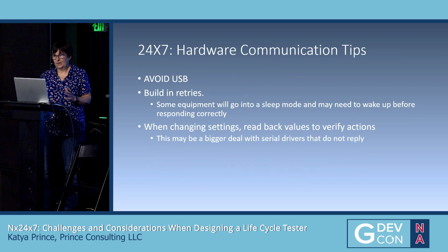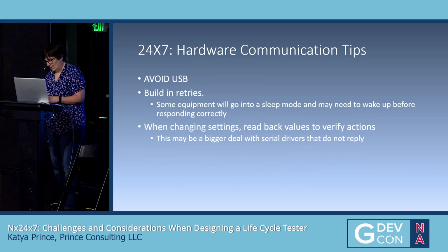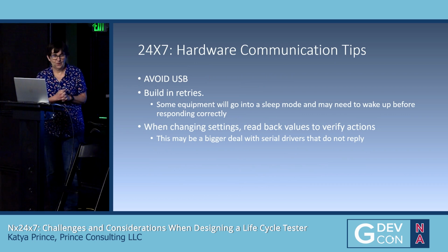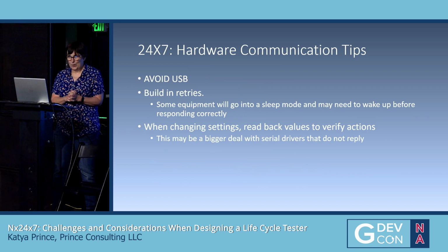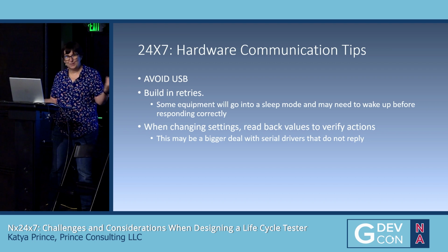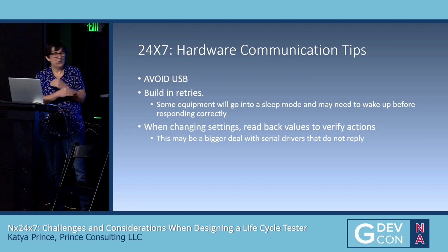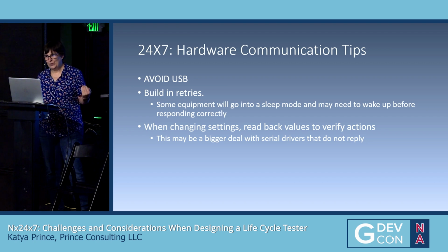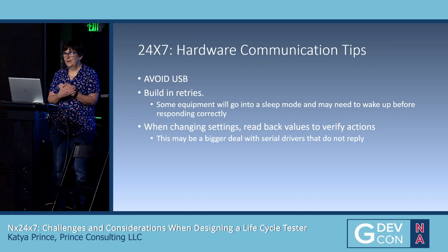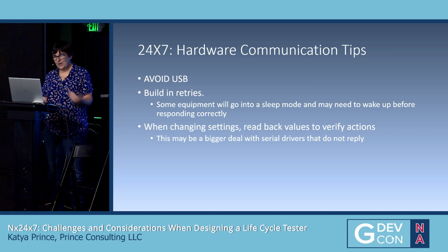Okay, so with that, let's switch a little bit and talk about hardware communication and some tips for that. I did a quick poll at the table, and they all agreed, no USB. Do not use USB, no matter what. I won't say avoid USB anymore. I'll just say don't use it. It's a very fragile bus. It's very easy to corrupt. LabVIEW can have a hard time trying to reestablish that communication. So especially for anything that's going to be running this long, don't use it. Find another way. Build in retries.